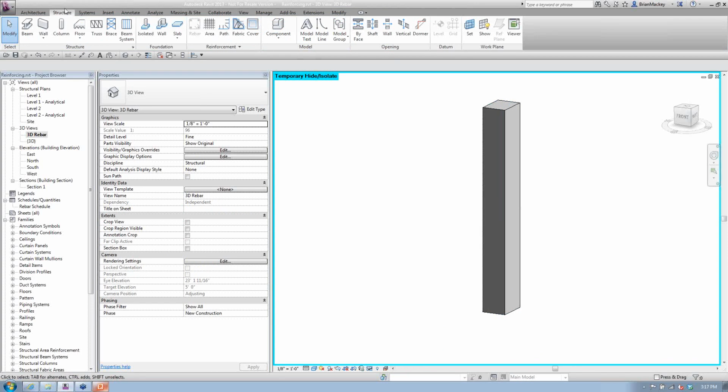If you need to start changing the different covers, you're going to notice that in your reinforcement panel, there's this actual cover button. So if I come up here and click the cover button, I can tell it to do the cover on the element, which is basically just going to give me the same properties that I have for the properties of it. But if I want to, I can go back and give myself the cover for individual faces. So now when I come here and say individual faces, I can pick on a face of the column.